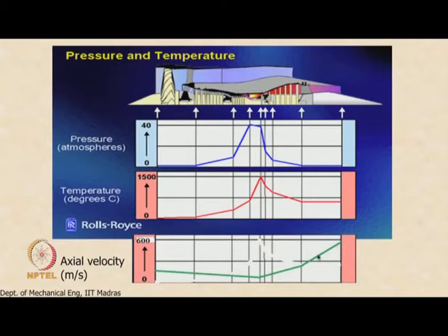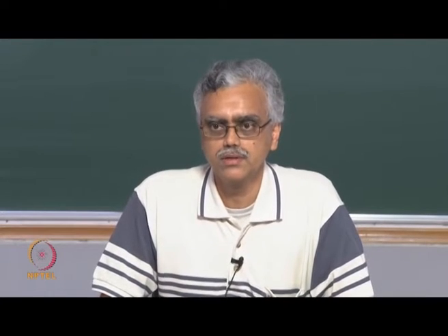Then in the nozzle you can see that the velocity increases to nearly 500 to 600 meters per second. Okay. But remember, the temperature of the air here is higher, so even 500 meters per second will still be only subsonic, not supersonic.